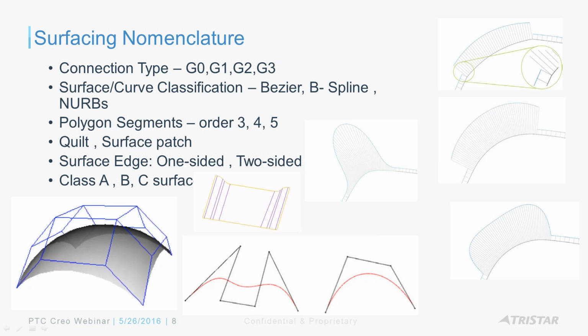So really, if you think about a surface model, right, you could create a surface model on its own using curves, right? That's what we normally do. However, many times what we call hybrid modeling, where you may want to marry the solid modeling and surface modeling features in such a way that you're working on a very complex area or a complex casting where the solid feature simply fails. The round and the draft, they just don't work, and you may have to do some patchwork using surfacing, right? So really the skill comes in making smooth transition from one surface to the next, right?